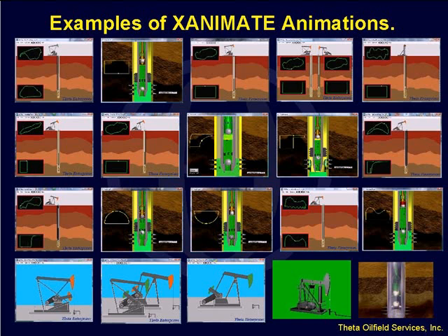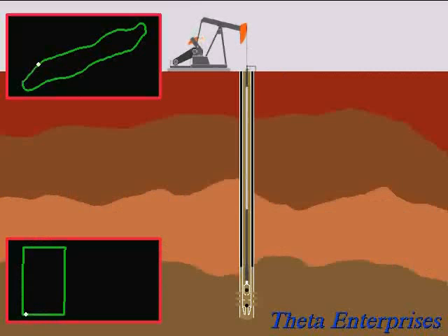resulting in excessive stretch. As a matter of fact, the stretch was so large when the well would pump off or get close to being pumped off that there was so much stretch in the rods that you hardly had any stroke at the pump. Here you basically have to go all the way to the top of the upstroke before the plunger moves up, because all you're doing is stretching the rods back and forth. You can see that very clearly here. So this is excessive under travel because of too much stretch in the fiberglass section.